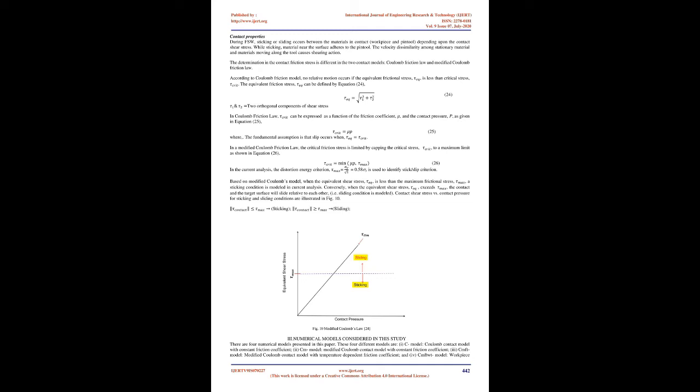Where the first term is the nodal temperature vector, the next is the temperature derivative with respect to time, the time-dependent conductivity matrix, the time-dependent capacitance matrix, and the heat vector with respect to time. The heat convection is a major source of heat loss in the plate during FSW. The heat loss from the side surface and top surface of the plate is calculated using equation 21.